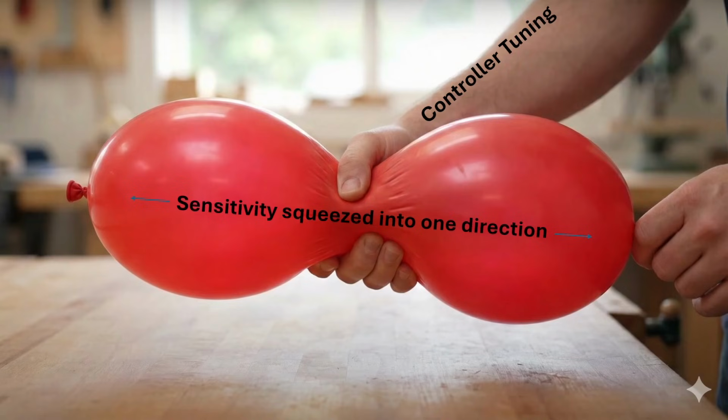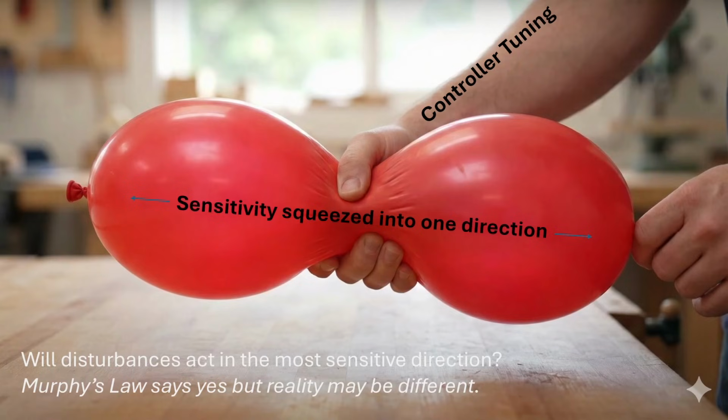This elongation represents sensitivity accumulating in the worst case maximum singular value direction. So will our system actually fail? Well, Murphy's Law says we must prepare for that perfect storm, where disturbances hit exactly along that axis. But in the real world, the system might never actually experience the full brunt of this worst case peak.